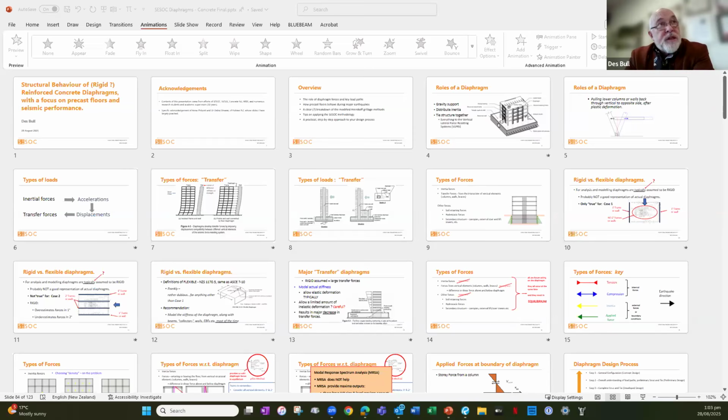And there's a bunch of rules in 3101 on how to detail and deal with bottle struts. Some simplifications in terms of doing the stress calcs, which is nice. Basically, it's the same stress calcs as prisms. But when we come to detailing orthogonal steel in walls or deep beams, there's a bunch of special requirements for areas which have bottle struts in them. Yeah, that's a really good answer.